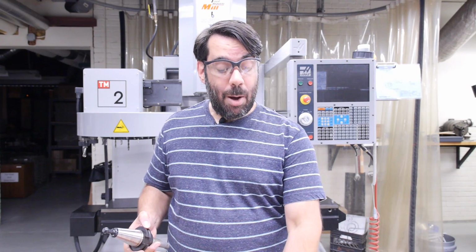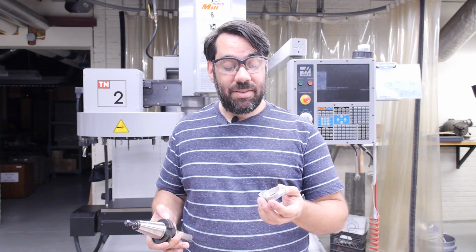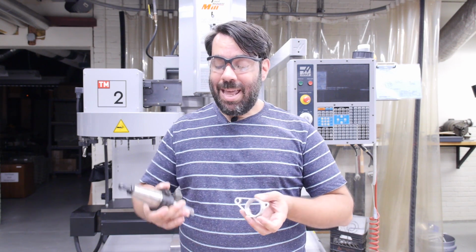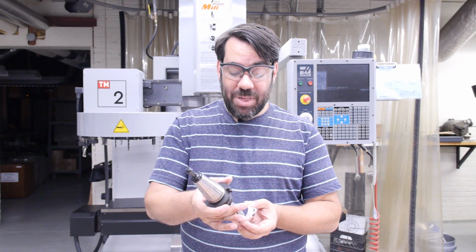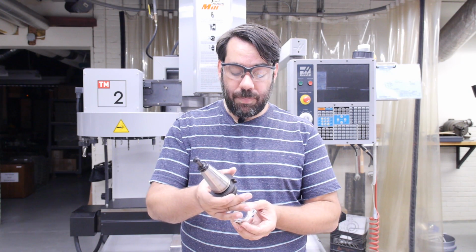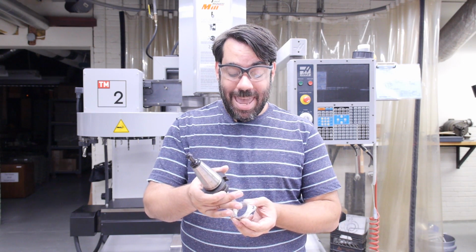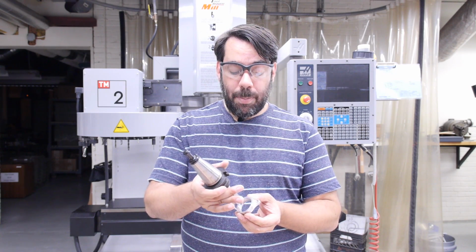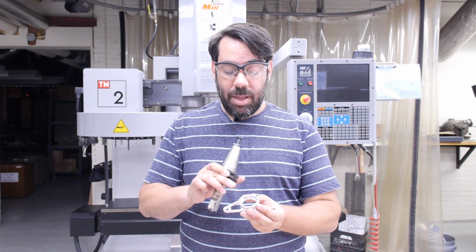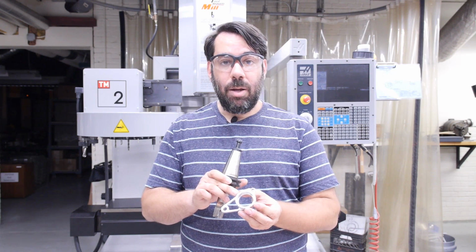A CNC machine, however, can accurately control multiple axes of simultaneous motion. So show the students an example of a CNC part, and then with the tool in your hand, explain that a CNC could move both the X and the Y axes of motion simultaneously in an accurate fashion in order to move this tool in the circular pattern required to produce this pocket, the circular pocket or circular bore.